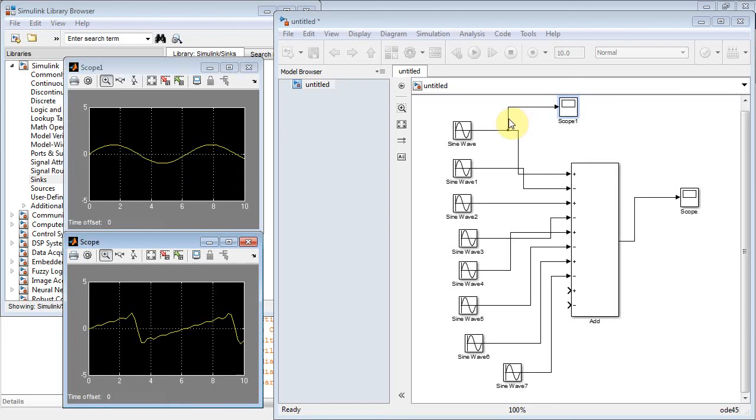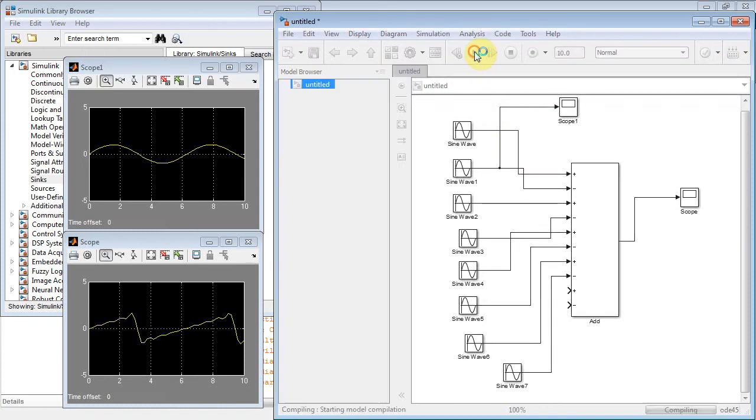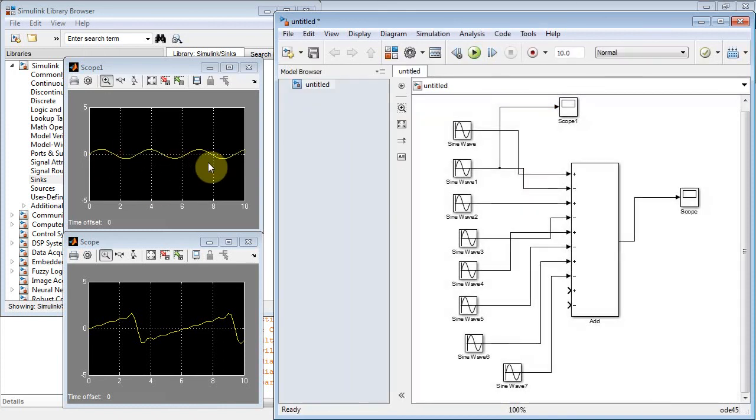That first one's generating a sine. Then I'd go over here, delete that, and check out my second signal. Run it again. Yep, there's a sine wave with twice the frequency. That one's good. Because it may be that you inadvertently changed some parameters and didn't realize it. You could check this term right here, and then run it, yep, and there's a higher frequency. Notice the amplitude shrinking down, so you can test it out.